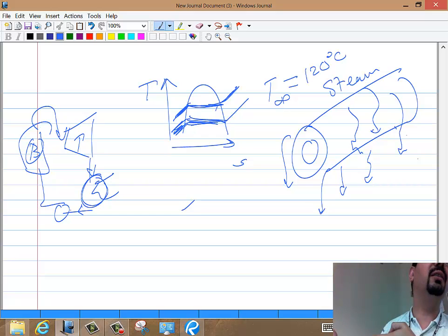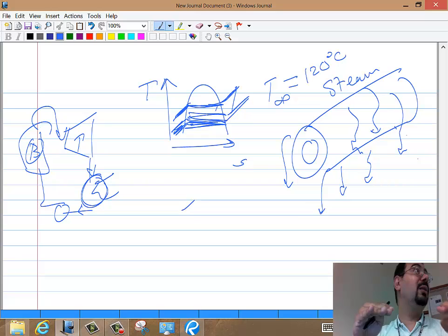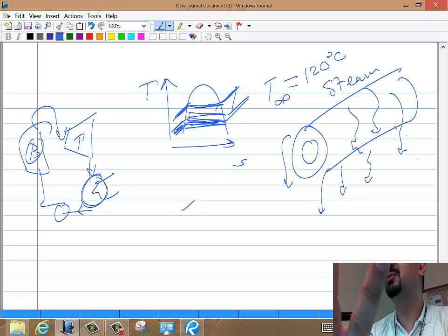Right? So if we are at 90 degrees, we cannot make the condenser cooler than 90 degrees. At 90 degrees, that would be the dream, and that requires a huge area actually. So probably the condenser will be sitting at 120. If it is at 120, that means the pressure will have to go up. That means less work available for our turbine, because we cannot take the pressure down. So the pressure is set by the temperature we are cooling it at, right? And the temperature is related to the cold fluid temperature, which is the air in Tulsa, right?